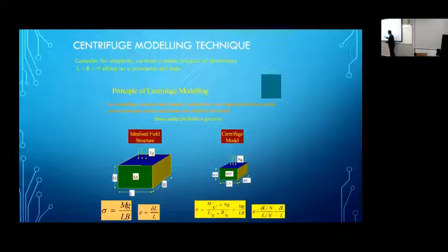All I'm going to do is to change the G from, instead of 1g, which is the normal gravitational level you have, to n times the G. Let's see what happens to the pressure. Now, the mass of this block, because I squashed in all directions, is going to be m over n cubed, obviously. So I'm taking m over n cubed and I'm putting it in a ng. So the vertical pressure is going to be m over n cubed times ng over the reduced length L over n and B over n. Now, miraculously, all the n's cancel out, and I'll get exactly mg over LB.